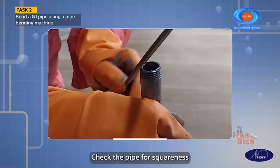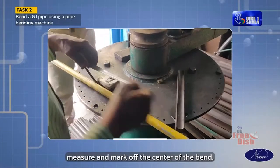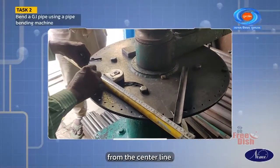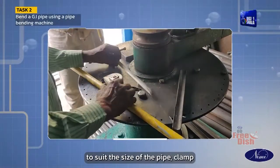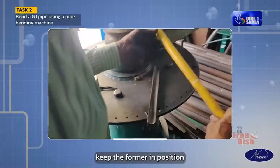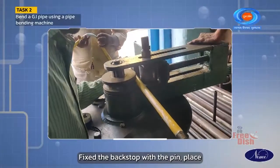Check the pipe for squareness and ensure it is free from burrs. Measure and mark off the center of the bend. Mark off the beginning and the end of the bend from the center line. Select the appropriate former to suit the size of the pipe. Clamp the bending machine in a bench vise. Keep the former in position and lock with a pin. Fix the backstop with a pin.